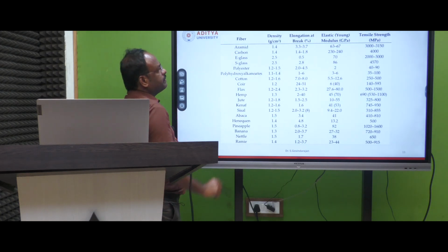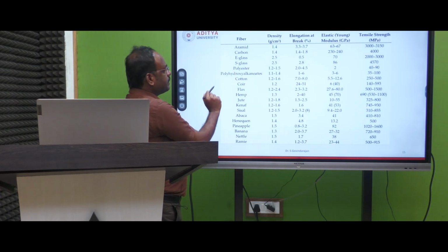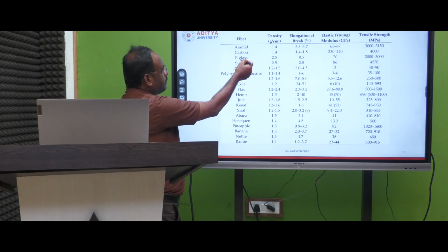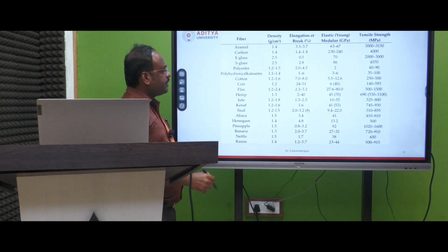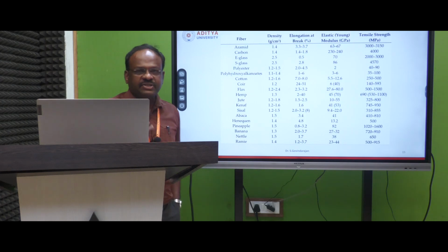Everything is mentioned here: aramid, carbon, E glass, S glass fiber, polyester, polypropylene and cotton, coir, flax. The first four are artificial fibers, and polyester and polypropylene are synthetic fibers. The remaining ones are natural fibers.